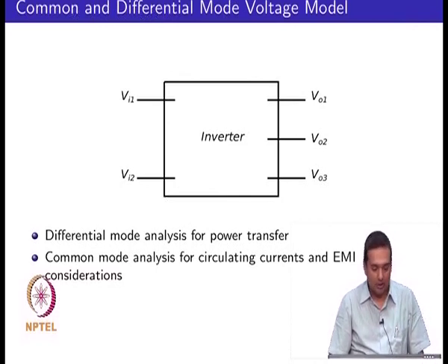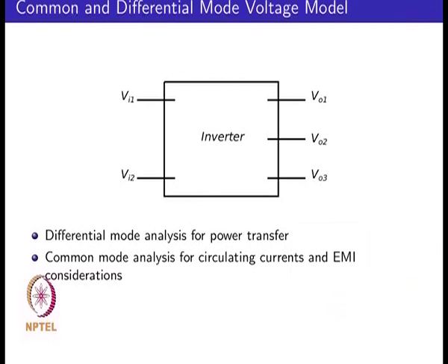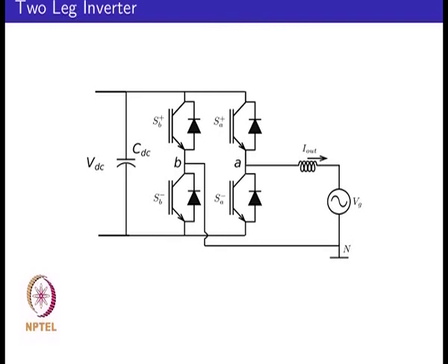The other thing we saw in the last class is that the common mode and differential mode analysis can be performed using both the switching model and the average model. And if you look at a single phase inverter, so this is a single phase 2-leg converter. Earlier we had looked at a single phase center tap capacitor converter. So, you could look at it from the common mode and differential mode analysis and look at how these circuits would behave. In particular, for the 2-leg converter, we looked at a